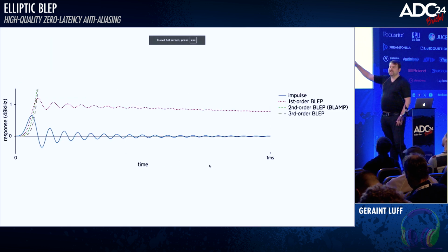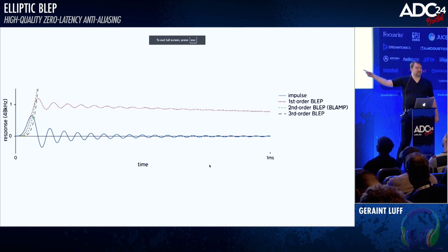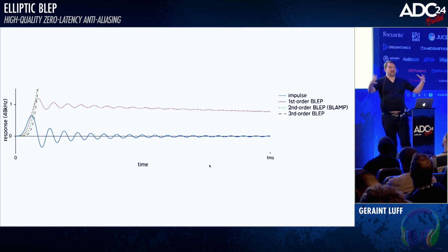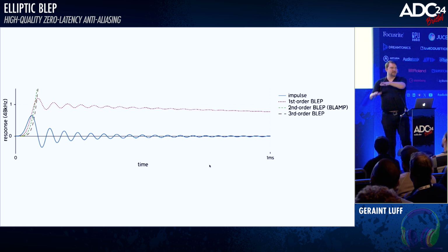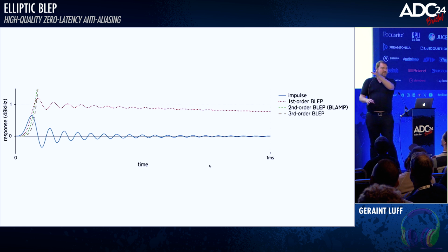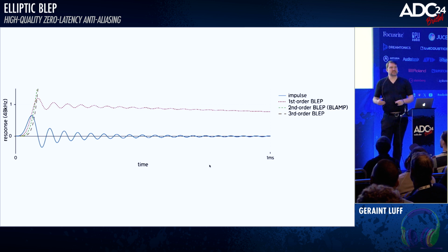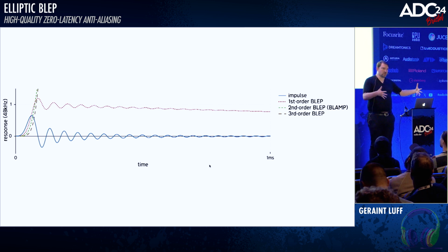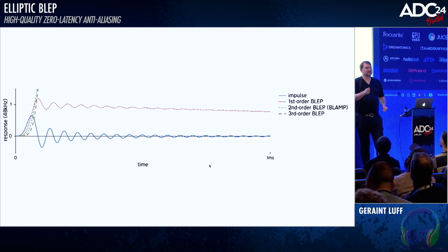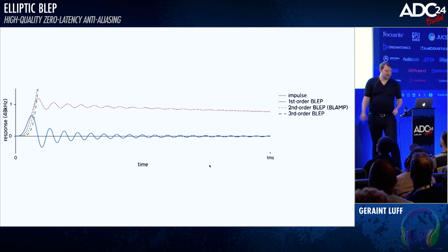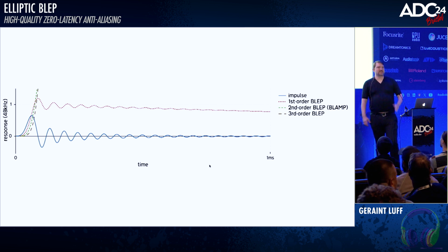So these are the impulse responses that we've now generated by designing our band-limiting low-pass, adding in a high-pass, then doing the decomposition into one-poles, and then integrating those one-poles individually, which just means giving them a little kick with different weights. So it's the same poles happening for all of them, the same one-pole filters, but we give them a different type of kick. And we can get this impulse, we can get its integral. The second and third order ones whiz off into infinity.